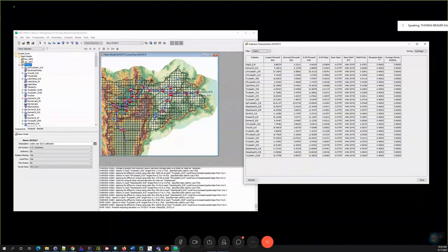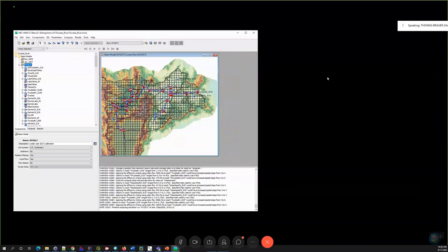And we actually have implemented in the code some reach characteristics, so things like length, slope, relief of a routing reach. I still need to hook that up in the interface, but it'll look very similar to this. And once we have these statistics, then they're accessible through that expression calculator that I just showed, which can be used in the global editors to help parameterize the model.